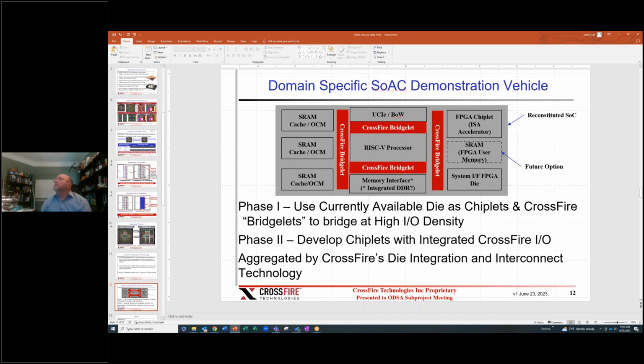And one last question: what is the map from this to Intel's EMIB? They show similar pictures. In terms of concept, it's very similar. TSMC also has something they call a local interconnect bridge, I think it is. The difference is that the I/O density on this would blow either one of those solutions away.